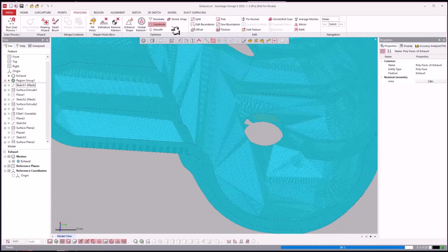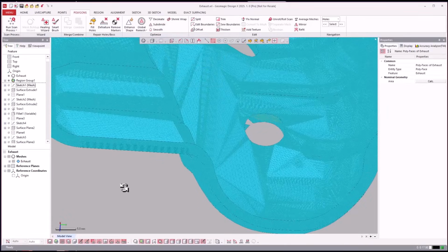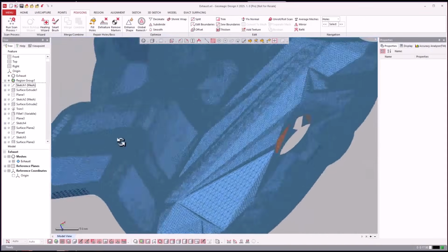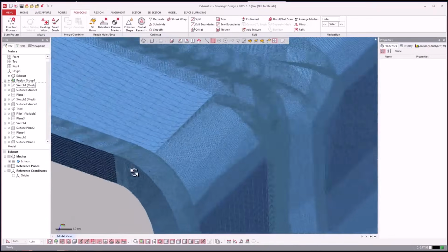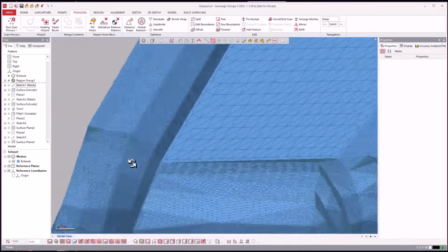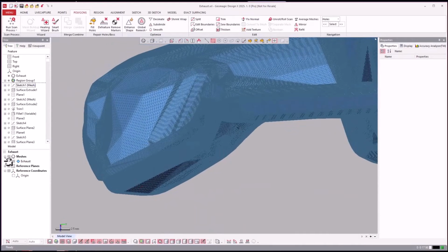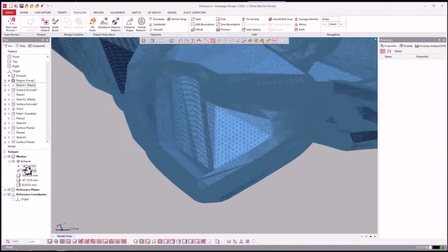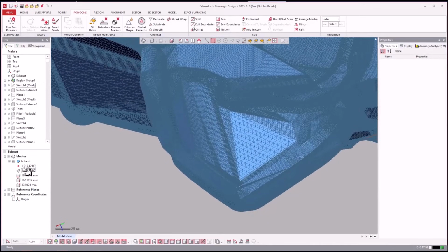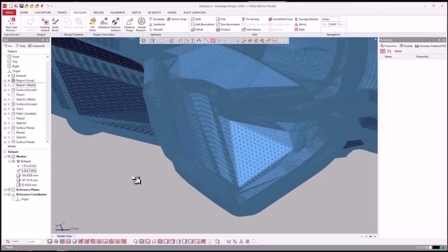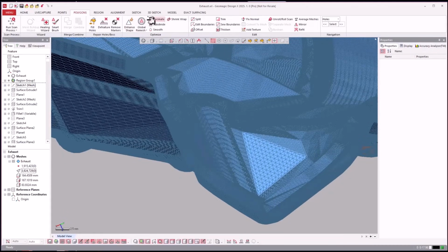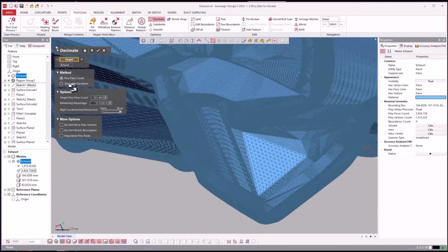So, yeah, subdivide is a really neat tool. Sometimes you could subdivide it up and then reduce it back down if you want to. If you want to decimate it back down to a certain level, to a certain exact triangle count. That's basically the reason why you'd want to do that. Because you look at, I raised this now to 3 million triangles. So you could then come back and say, I want to reduce it back down to 1 or whatever, like this. We'll go ahead and do it. Why not?